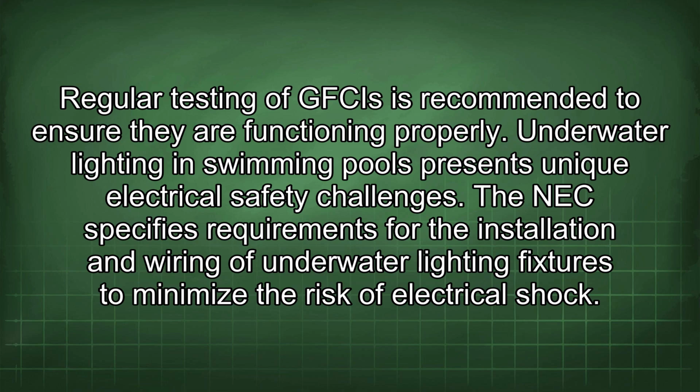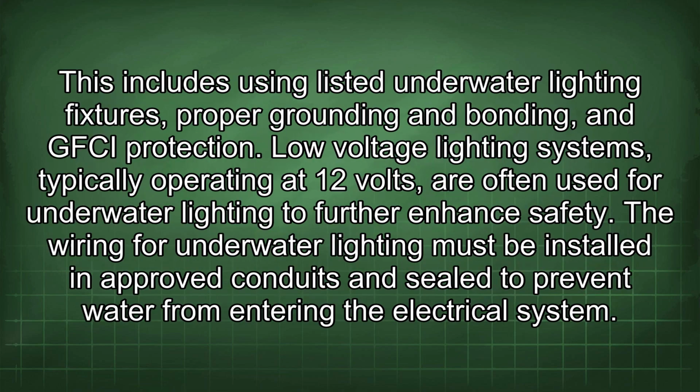Underwater lighting in swimming pools presents unique electrical safety challenges. The NEC specifies requirements for the installation and wiring of underwater lighting fixtures to minimize the risk of electrical shock. This includes using listed underwater lighting fixtures, proper grounding and bonding, and GFCI protection. Low voltage lighting systems, typically operating at 12 volts, are often used for underwater lighting to further enhance safety. The wiring for underwater lighting must be installed in approved conduits and sealed to prevent water from entering the electrical system.